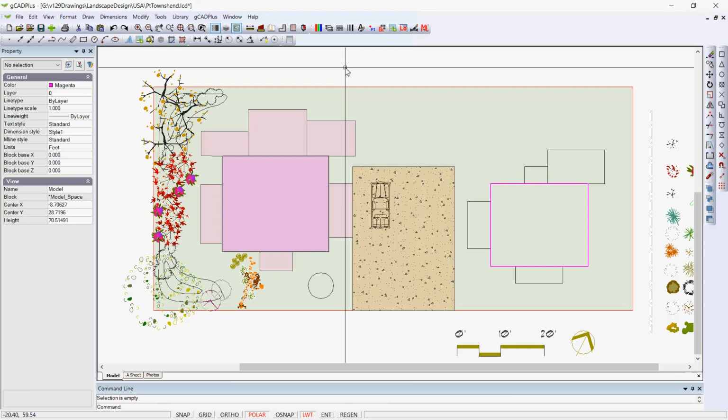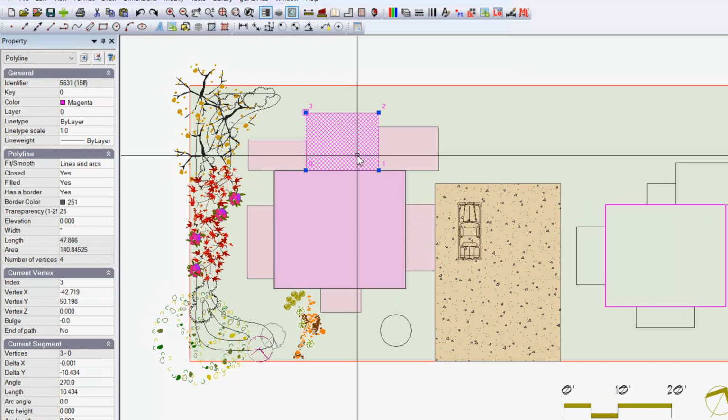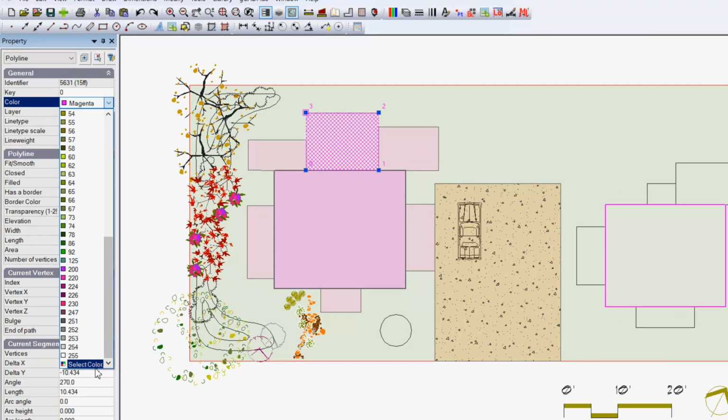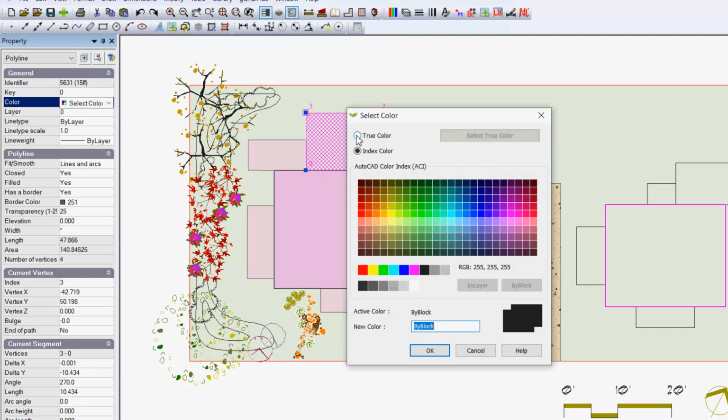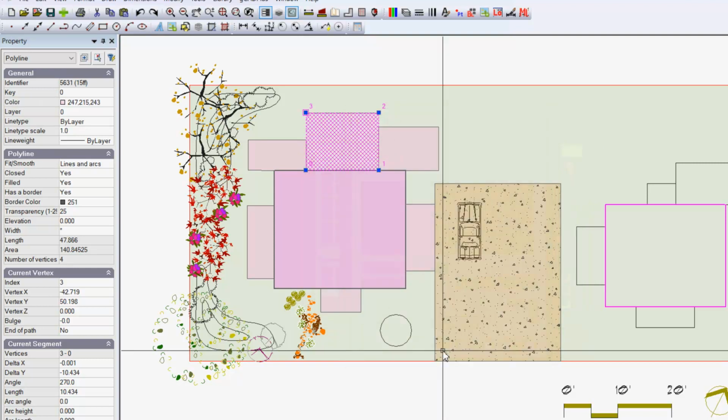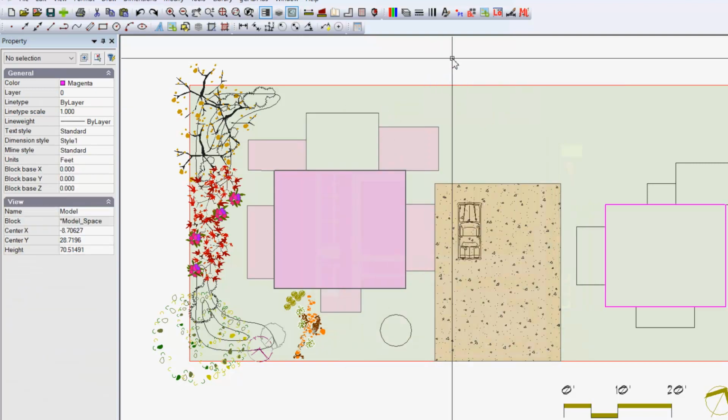a long time. And if you want quick high resolution PDFs, it's best to set colour by picking a specific colour. So rather than magenta, you would come down here, go to select colour, pick true colour, and come into the sort of magenta area about here, and then pick a light colour like so and apply that. Let me unselect all.